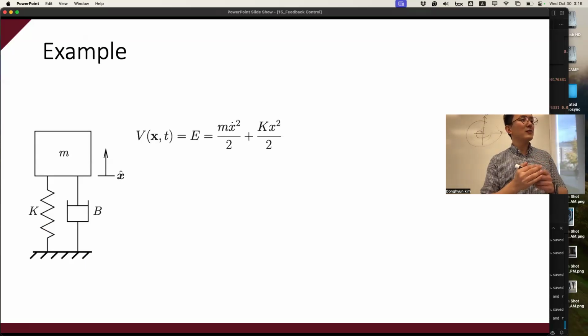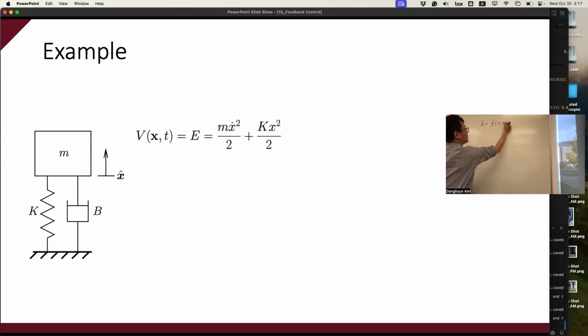Relate to what we're doing in terms of feedback control. Ah, good question. We're not going to do this in this example, but because you asked: our system dynamics is going to end up being x double dot equals f of x and x dot, t. If I define the Lyapunov function, by the way, this x is a state, x and x dot, as a function of x(t), then when you take the time derivative, you're going to see the x double dot somewhere in this term.